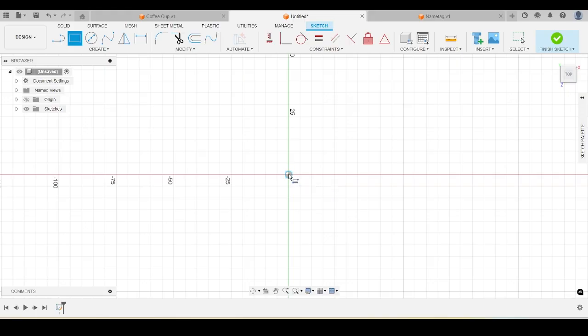So what I'm going to do now is click, and I'm going to find that if I start dragging my mouse across, I get a rectangle. And hopefully you guys can see all the dimensioning measurements that are coming up. Again, if not, I'm hoping you guys can follow along at home on your own device. But you'll notice that when I drag it across, the numbers change. It automatically snaps to our grid, which is super handy if I was going to make a 50 by 25 mil shape, which is where I'm sitting at the moment. So 50 millimeters across, 25 millimeters up.